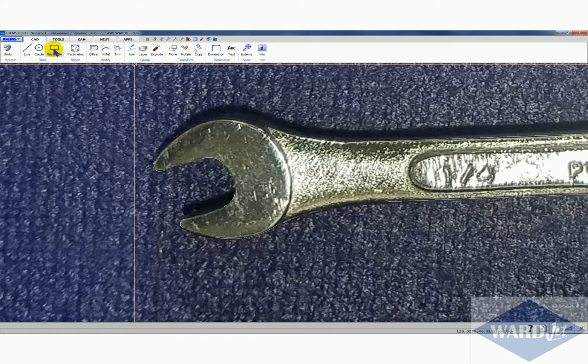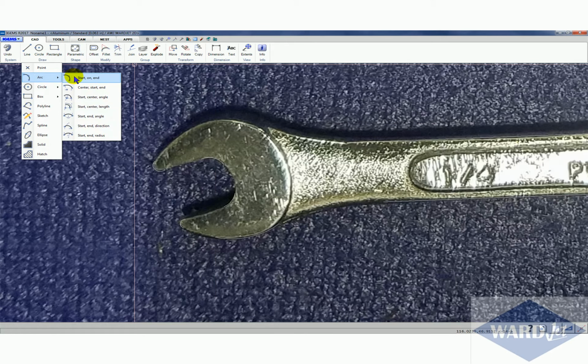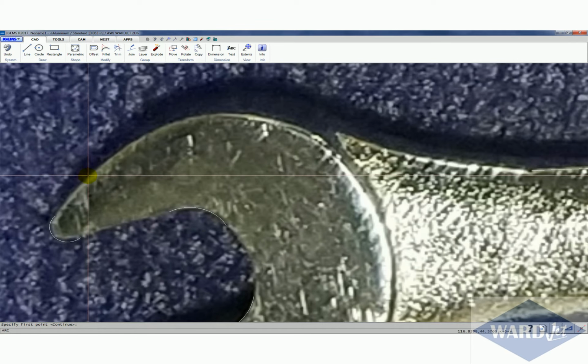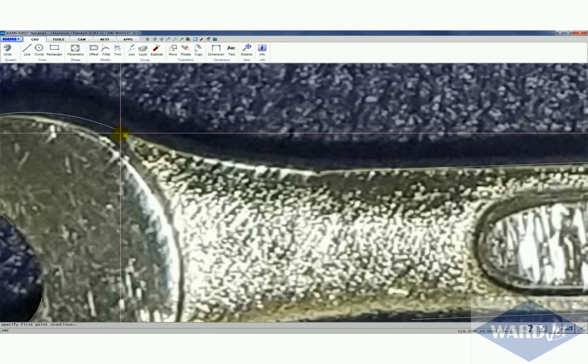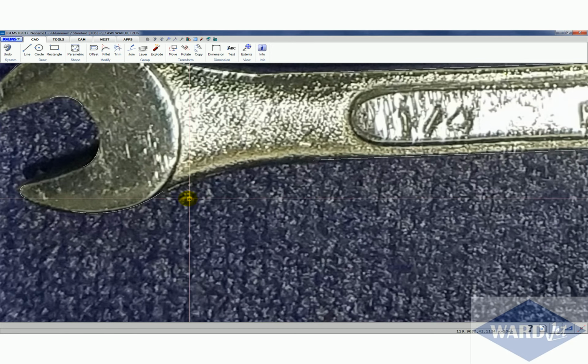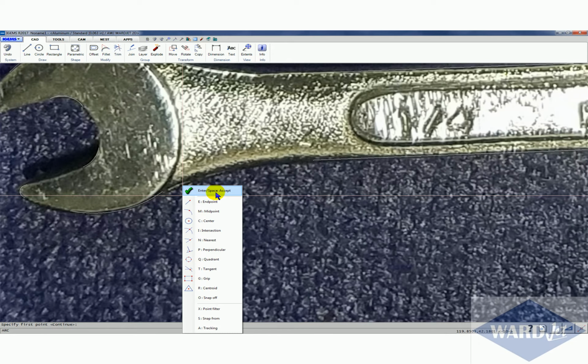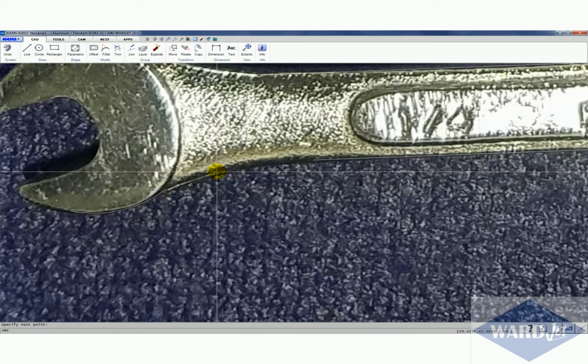And then when I have some points like that, then I'll be able to just use the line command and connect things. So I'll do another one up here, from the endpoint of there, go to there, and go to the endpoint of there. And I can do another arc down here, starting at the endpoint of here, and there, and ending there.